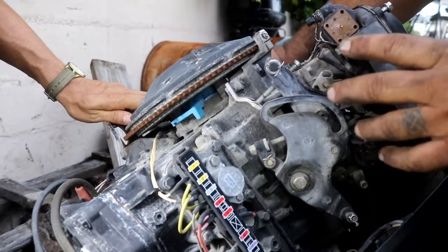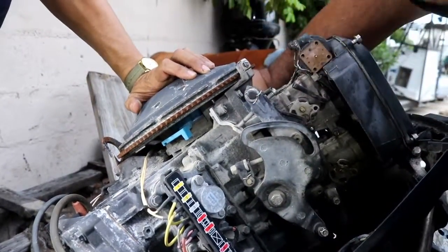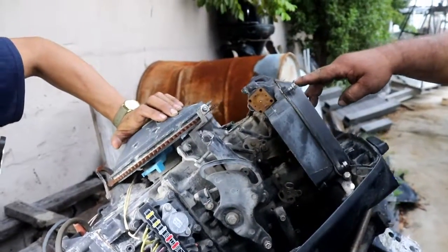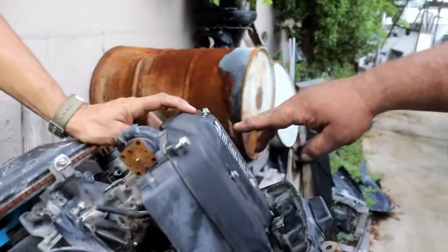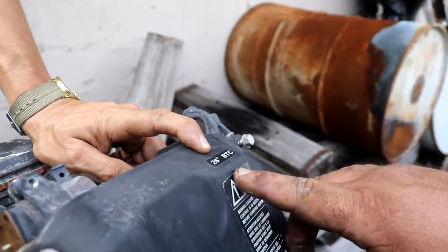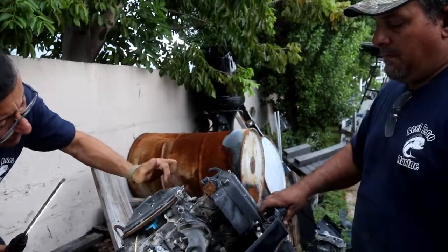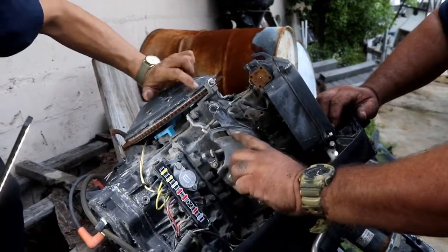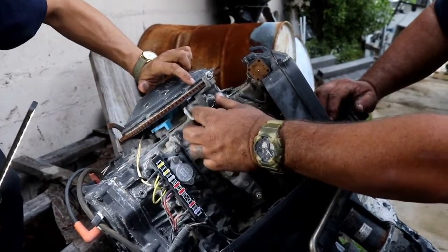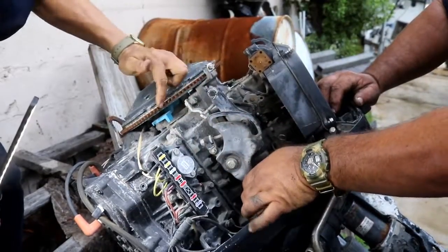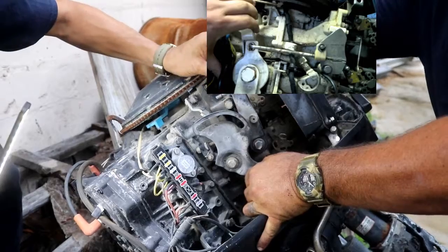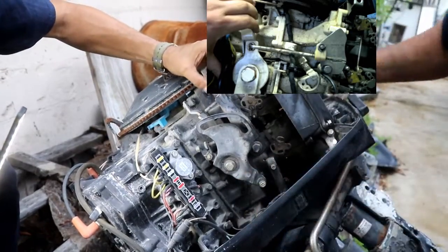So at low RPMs, it'll tell you, let's say 4 degrees, and then at wide open throttle, it tells you 26 degrees before top center. This is the recommended by the manufacturer. And how is the movement? The movement with the throttle is like this. Again, there's a cam that goes in here with a rod that goes from here to here. So when you move this, that one moves exactly at the same time.